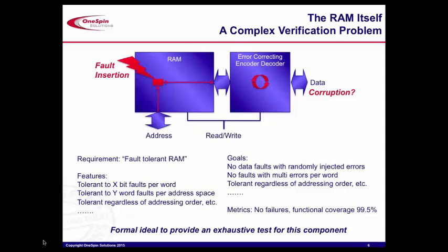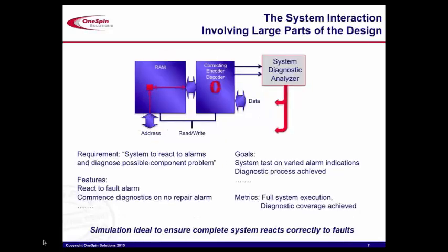Otherwise, you fail some of the new automotive safety standards like 26262, which basically says you've got to do all testing without changing any design code. So you need to start to apply some more advanced techniques such as fault injection, which you could do with a Verilog force statement, or in formal you can actually apply faults without changing the design and do it with the faults being exhaustively applied across the memory. Okay, so we're testing both our system and the component itself using different techniques here.